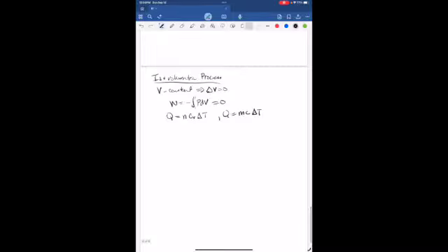And same thing down here. So we have the two cases. The change in internal energy is n C_V delta T minus zero, since the work is zero. And same thing here: the change in internal energy would be m c delta T. So you really have to choose the formula according to whether you're working with a gas or a solid or liquid. But anyways, that's an isovolumetric process.